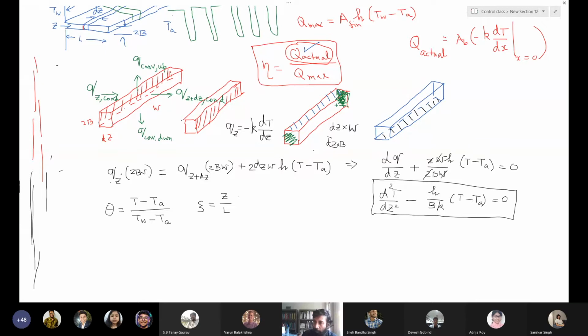So when you solve an equation, most of the time, or sometimes I should say, you do not have exact analytical solution of an equation. You need to do various kinds of approximations, order of magnitude estimates, and these things in engineering or in science in general. So for those kinds of things, it's very beneficial to know what is the range of certain variables. So the primary purpose of non-dimensionalization is to bring the range of variables from 0 to 1. It's not always successful, as we'll see, but still non-dimensionalization helps to give a certain bound to the variable.